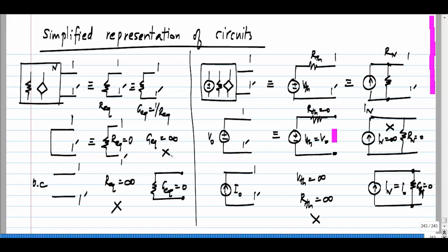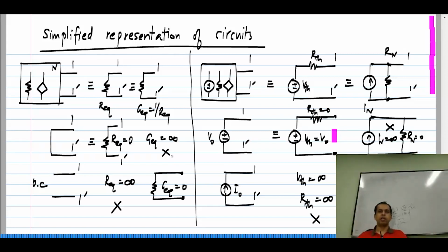So, those are just preliminaries. Now, I will go into two-port parameters, which are basically a way of describing circuits where two pairs of terminals are exposed to you, and you can describe the electrical behavior at those two pairs of terminals with an equivalent circuit. As usual, the internal circuit can be very complicated, but as long as you are given access to only those pairs of terminals, whether you use the full complicated circuit or the equivalent circuit, there will be no difference.